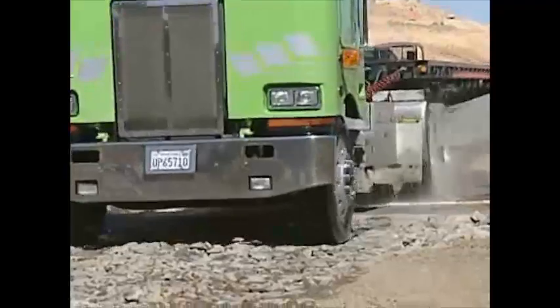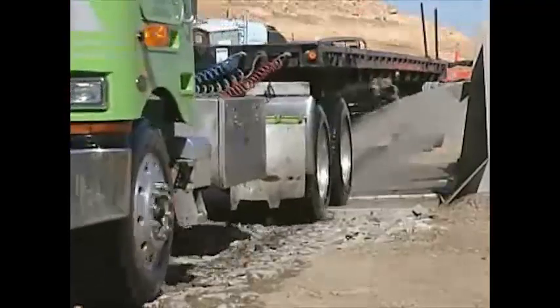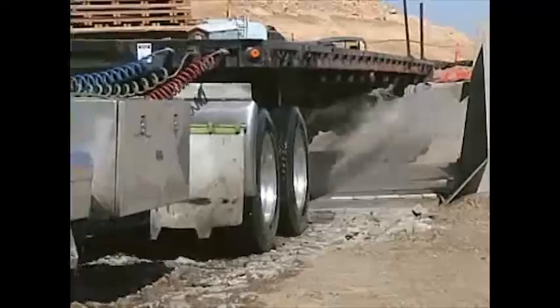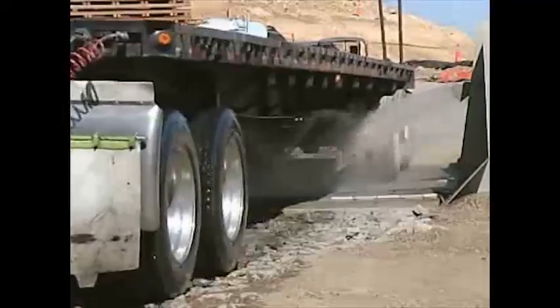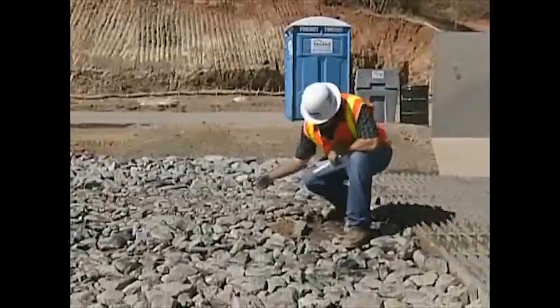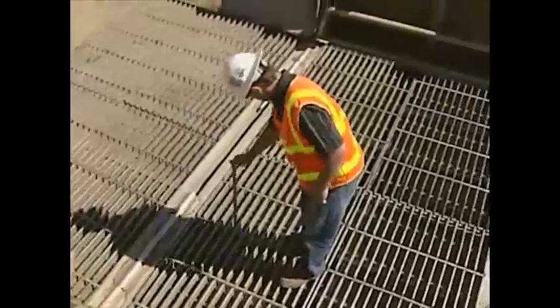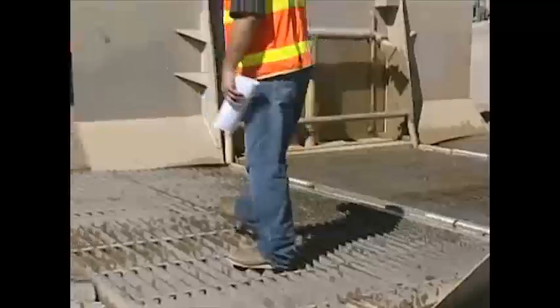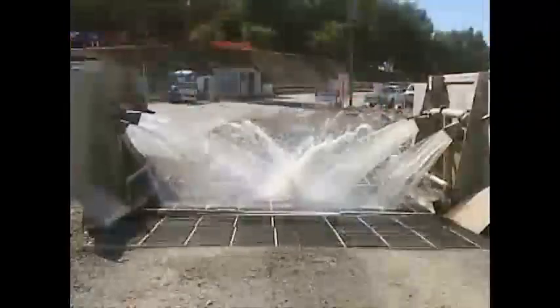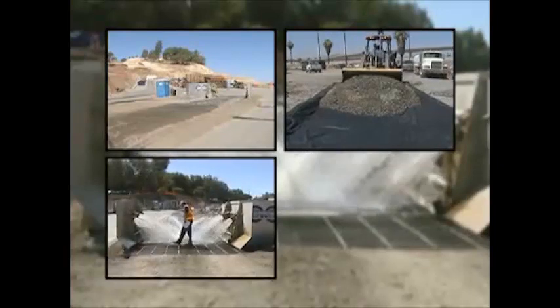It is the contractor's responsibility to maintain the tire wash on a routine basis. Let's go through some of the typical problems that are encountered at tire washes and the associated maintenance solutions. If the geotextile fabric becomes torn, the contractor must replace the fabric and aggregate. The contractor must also repair blocked or degraded drainage ditches and remove accumulated sediment in the wash rack and sediment trap to maintain system performance and effectiveness. Remember, proper BMP function depends on proper selection, installation, inspection, and maintenance.